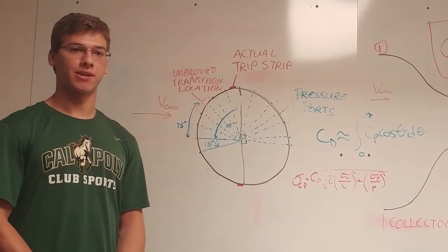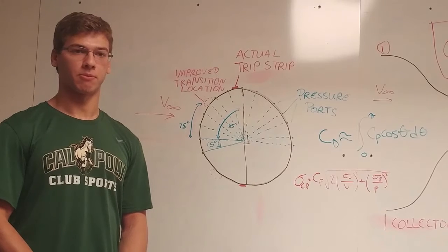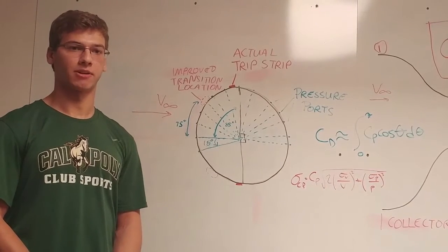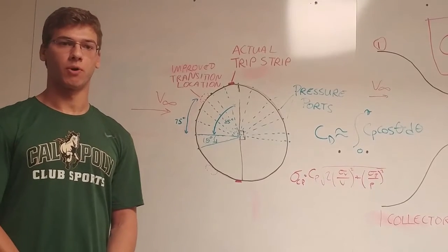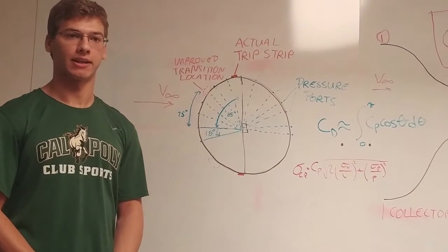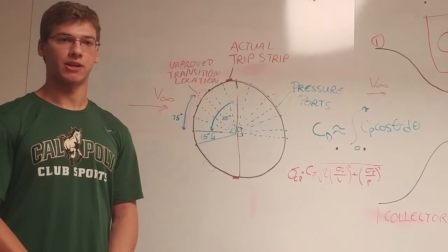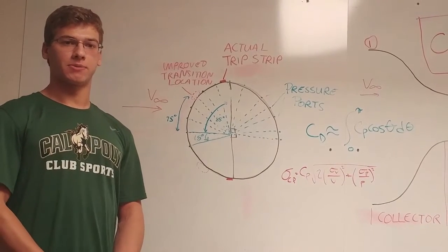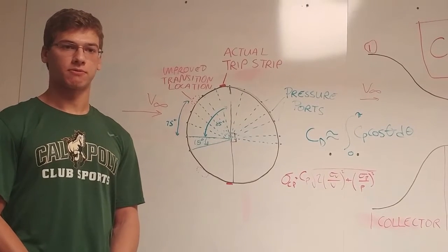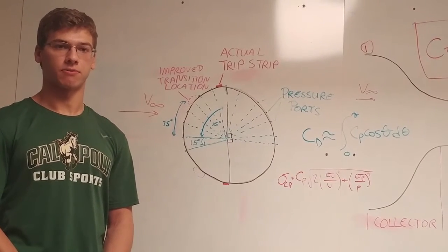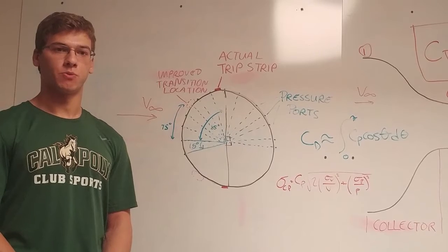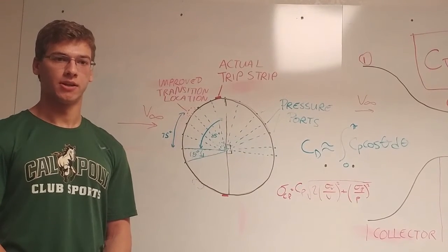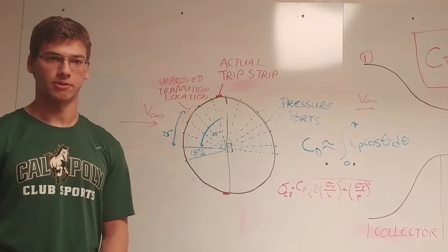For each of the 4 cases mentioned, we ran the test 3 times in order to obtain repeatability with the data. With our velocities and with the cylinder diameter about 4.5 inches or 0.1143 meters, as well as with our calculated ambient conditions, or density from pressure and temperature, as well as an estimated dynamic viscosity, we were able to obtain Reynolds numbers in the range of 53,000 for the slower case and 180,000 for the faster case. These are both values which fall in the range of laminar to low transitional for a flow over a cylinder, assuming the flow does not possess any unwanted disturbances.